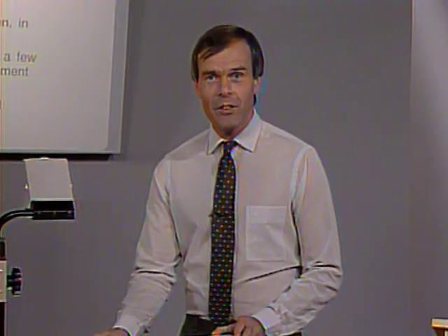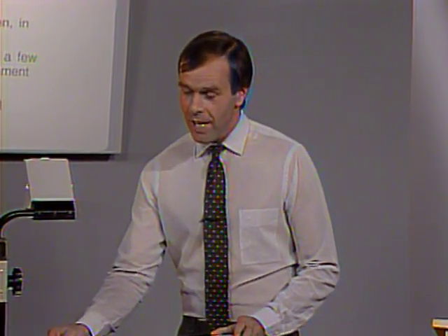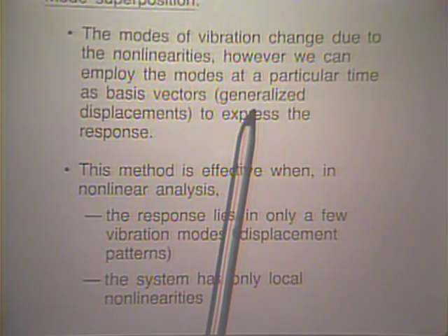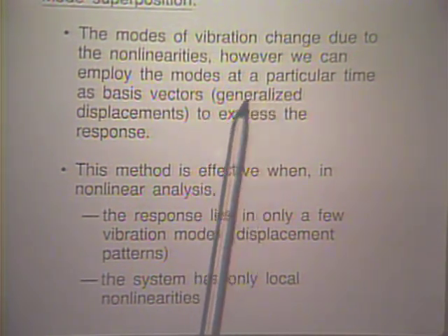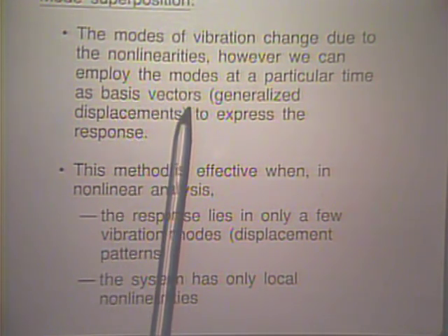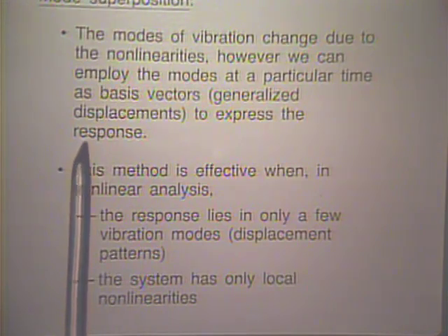However, we can extend that method directly to nonlinear analysis if we recognize that the mode shape vectors of the system at a particular time can be used as generalized displacements or basis vectors to express the response at any other time as well.